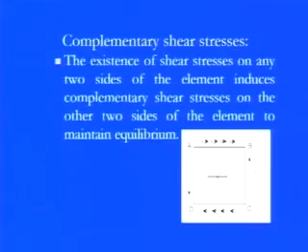Now just 6 components are well defined, and we can say that the stress tensor is well defined, if the object is symmetric, by 6 different components: 3 normal stress and 3 shear stress components. Now come to another point in the shear stress only, that is complementary shear stress. As we have discussed, the shear stress is a plane stress. Plane stress means it is always acting in either the xy, yz or zx plane, as we have seen in the previous part.